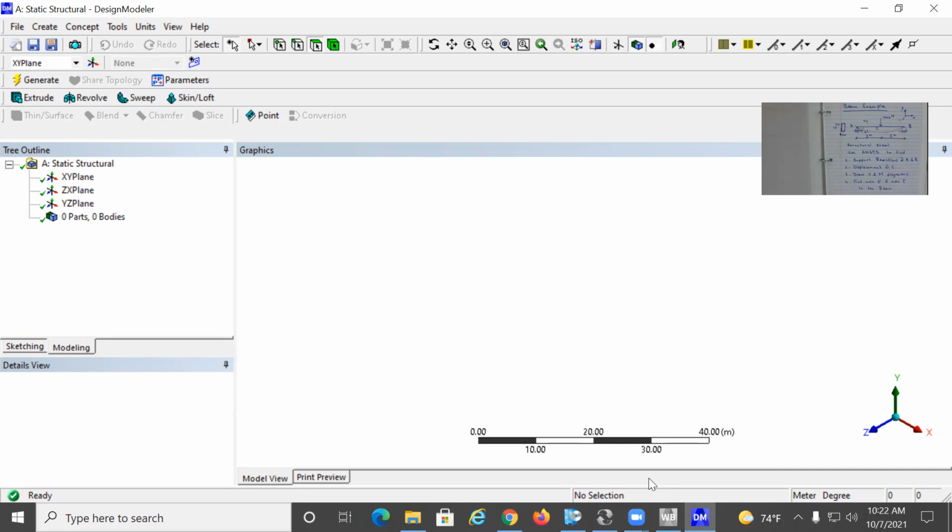I'm not just creating a CAD model, but I'm creating a CAD model for simulation. So I have to create entities that I don't need for my geometry, but I need for my loads or constraints. So with that being said, we know that we are going to create 3 points and 2 line concepts.